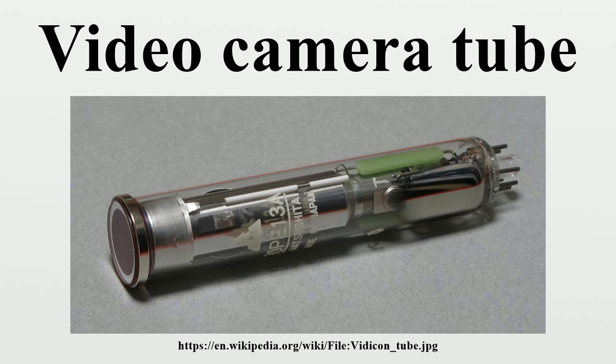Operation: the optical system of the image dissector focuses an image onto a photocathode mounted inside a high vacuum. As light strikes the photocathode, electrons are emitted in proportion to the intensity of the light. The entire electron image is deflected, and a scanning aperture permits only those electrons emanating from a very small area of the photocathode to be captured by the detector at any given time.